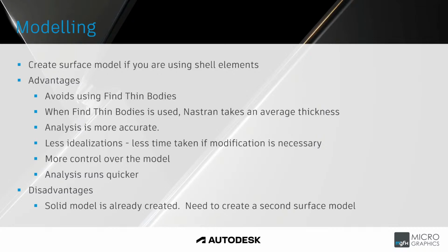So this is something that, if you know that you're going to be using a lot of surfaces, so you're going to have surface idealizations, rather recreate the entire model as an FEA model separate to your normal model. Okay, you'll find that you'll save so much time, especially when it comes to having to recreate or modify your component to maybe get different results to enhance your parts and assembly.